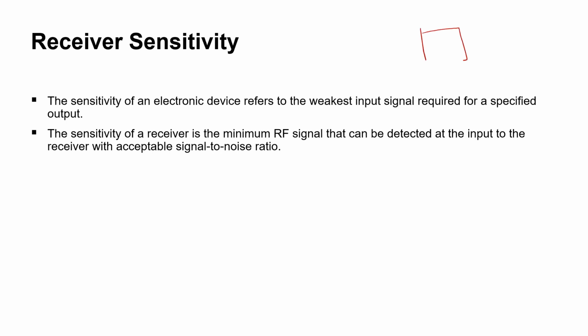Imagine if we have one receiver with multiple electronic high frequency systems and we have one antenna, then we are actually interested in the minimum signal to noise ratio at this stage, for which we can get a signal that is powerful enough that our detectors or our analog to digital converters can actually make sense out of it.